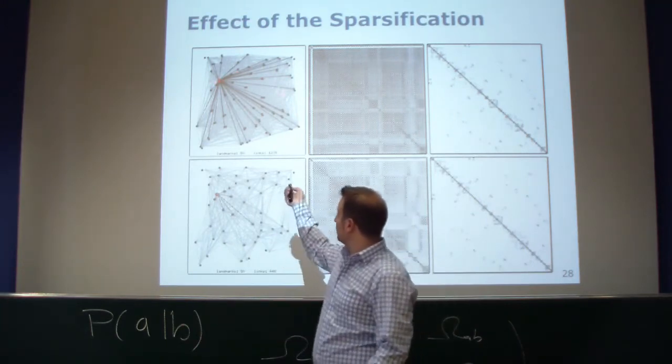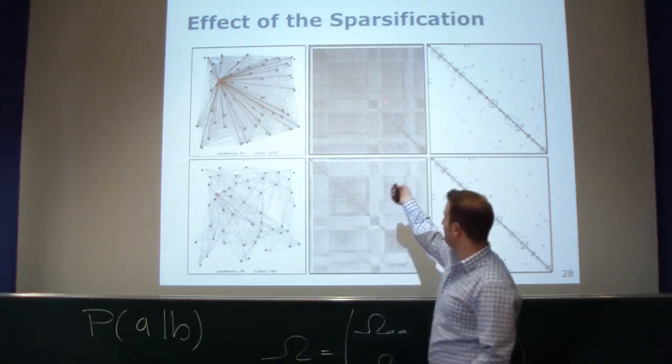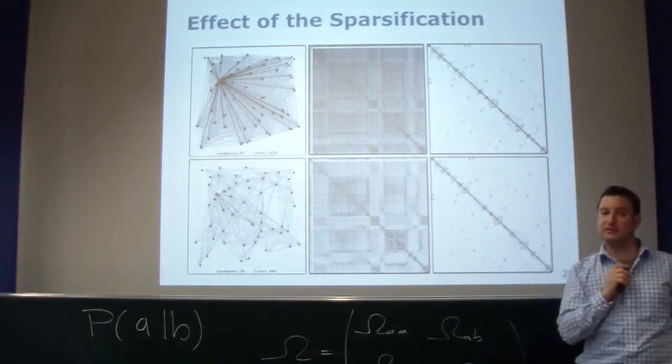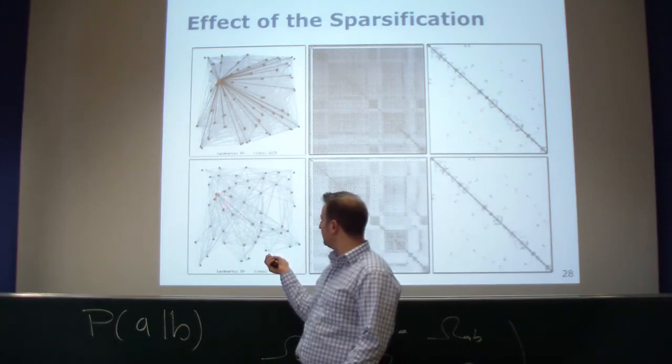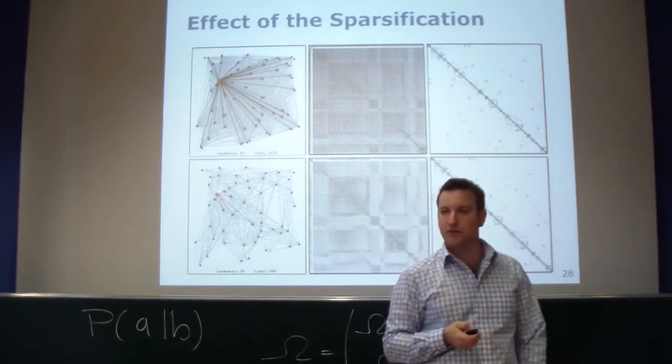You see the closest link to every landmark. All those landmarks are densely connected with links. This is how the covariance matrix looks, and this is how the information matrix looks. This is what the SEIF does in this case for 6 active landmarks.